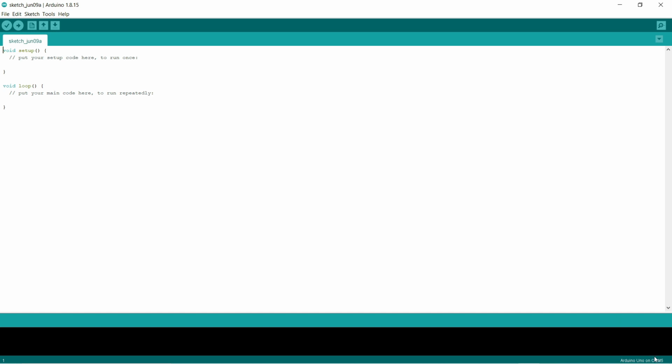So you can see your Arduino COM5. So you can see here, we already discussed that. COM4 is nothing but COM5. So in your case, it should be COM3. Okay, no problem. So now we need to actually upload the standard firmware code. Before uploading the code, you need to also connect your Arduino board. So this time I'm going to connect that. Our Arduino is connected. So I'm going to click here to upload the code. You can see here compiling the sketch, and it will upload the code, uploading, done uploading. So our code uploading is done.